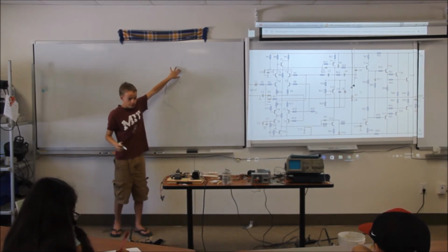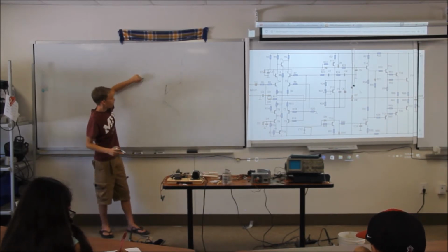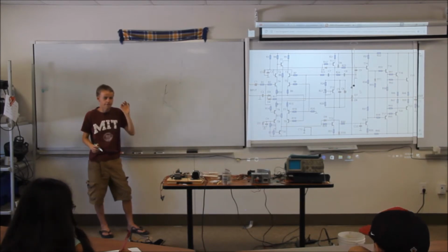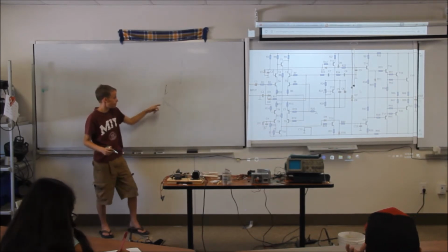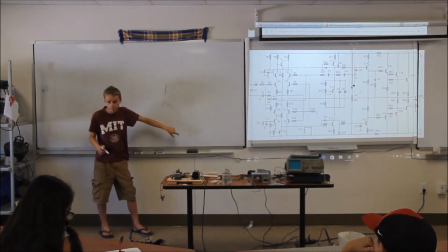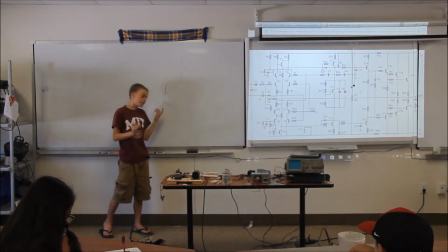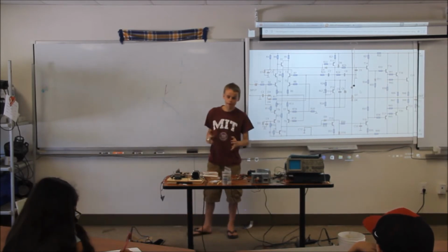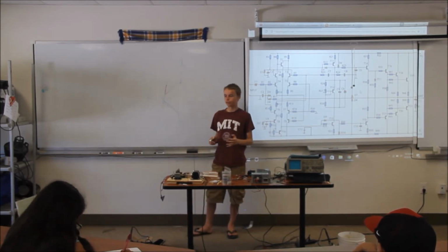And this circuit will be allowed to turn on if you allow current to flow through the base. And even if it's just a tiny amount of current flowing through the base, it'll allow a large amount of current to flow through the collector to the emitter of the transistor. And so that's pretty much how the most basic of the basic NPN transistors work.